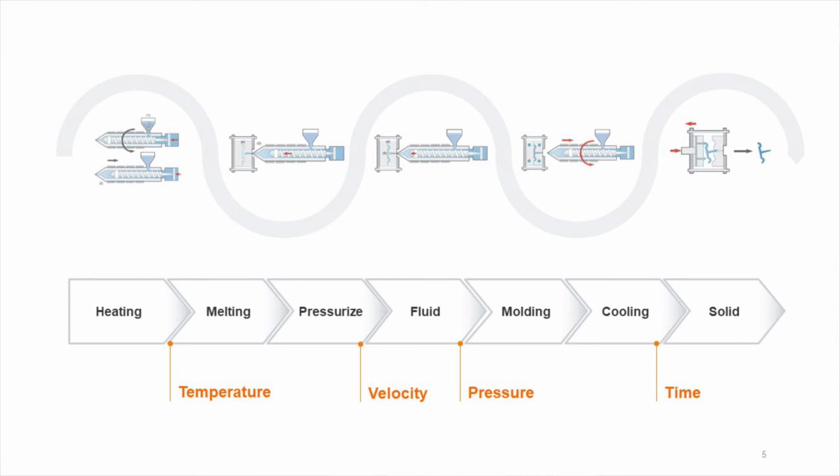When the melt reaches the plasticized amount, the screw will move forward and push the melt into the cavity. While the melt undergoes increasing pressure rapidly, the melt maintains a fluid state and continues to fill the cavity to form the molded part. Meanwhile, the heat is passed to the mold from the plastics, which cools down the melt to become the